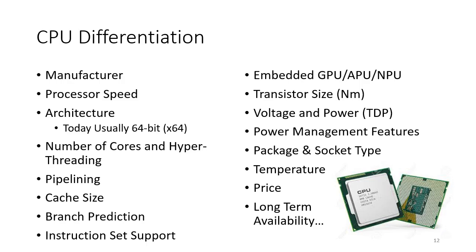Again, that's something that you have to rely on your vendor for, but there are some versions of chips that are made for longer than others. With a consumer grade chip, it's maybe only made by the manufacturer for 1 or 2 years, and then it will be replaced very quickly. So if you're buying an industrial PC, your vendor will normally negotiate with the manufacturer of the chip, and they will use a chip that has a much longer life, specifically intended for these more industrialized environments. What the vendor would normally be looking for is a commitment from the manufacturer for at least 5 years supply, and then they might buy more to keep them going for longer extended life. But ideally, you'd be looking for a chip that's going to be made for 10 years.